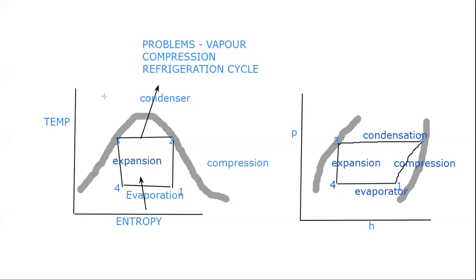Look at this cycle, 2 to 3, where will the liquid be? Liquid will be at point number 3. I'm putting the arrow on the whiteboard. Because after condensation it will be in liquid form, correct? So the 60 bar liquid enthalpy is hf3.